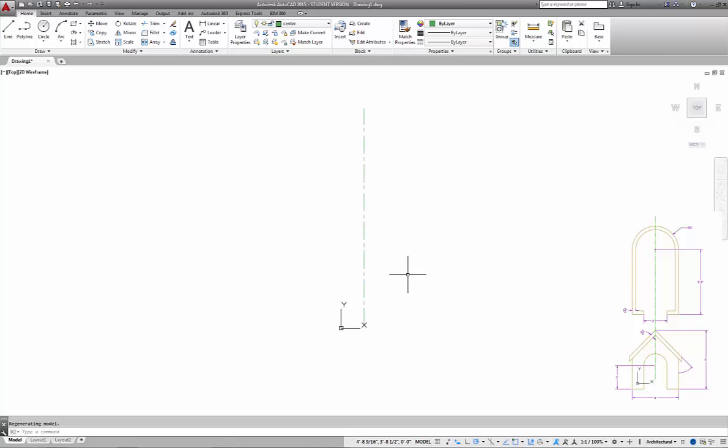So now if it was a 12, that looks much better with the number of breaks, but let's work it backwards. So if a 1/4 inch equals a foot is 48, and half of that is 24, and we just did half of that 24, then we would actually be working at 1/2 inch equals 1 foot, which would equal 24, and divide that by 2, which would be 12. So in essence, our plotting scale will be a 1/2 inch equals a foot, which is what our line type is based at. Hopefully that makes sense with that mathematics.